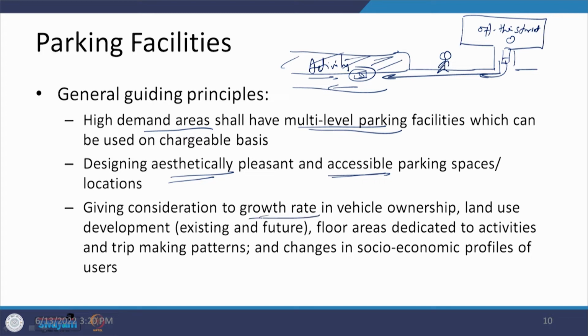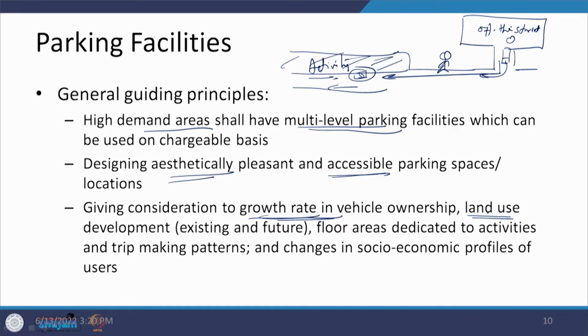Then growth rates in the vehicle ownership also need to be taken into consideration. Along with that, we have to see the master plan of that area, which will define how the land uses are going to change or increase in their sizes, and that is going to define the amount of activity which will be there, the generation, and the attraction in that area. These things are further going to define the parking requirements. So, we have to take all of these things into consideration.